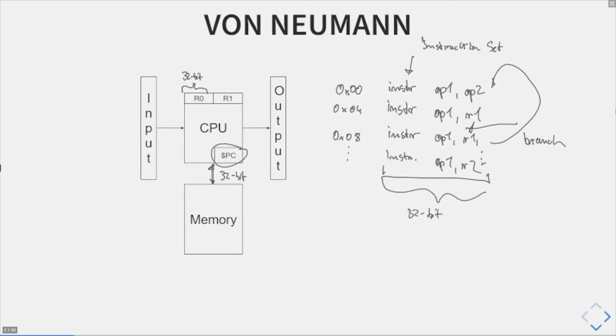That's also the difference between the ARM, x86, and RISC-V CPUs: how those 32 bits actually designate an instruction. So this is a particular bit pattern that you have, for example, if you want to encode a branch instruction. First of all, you encode that it is a branch instruction with a particular bit pattern.